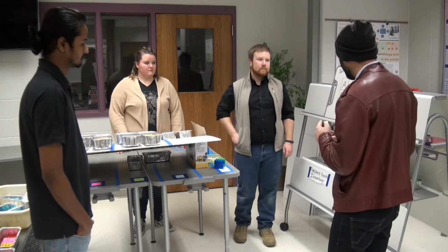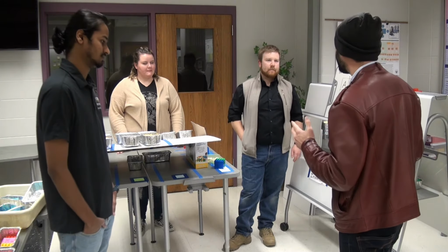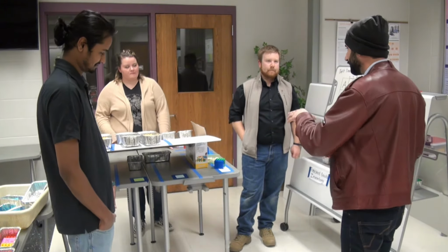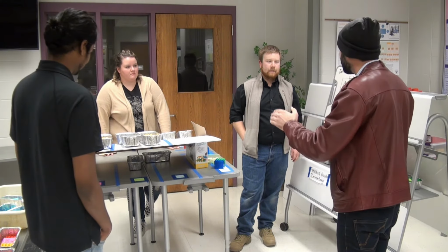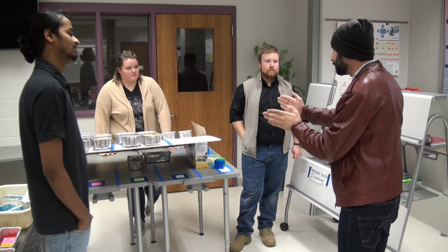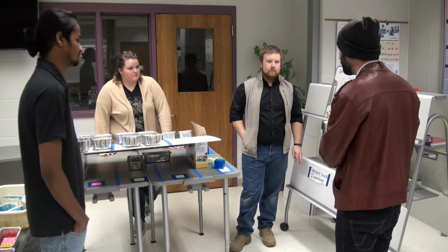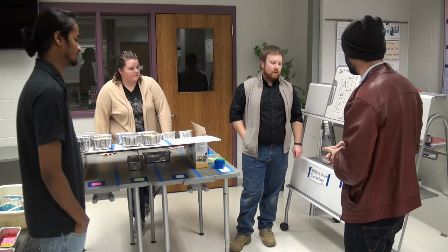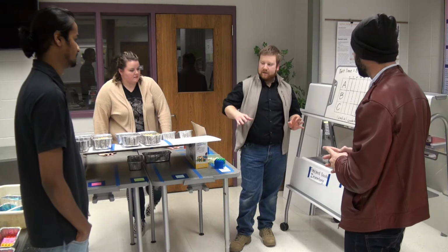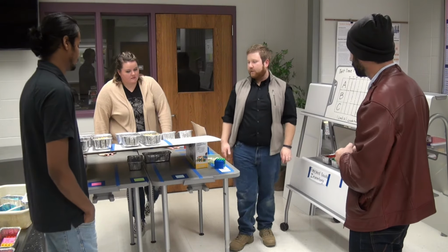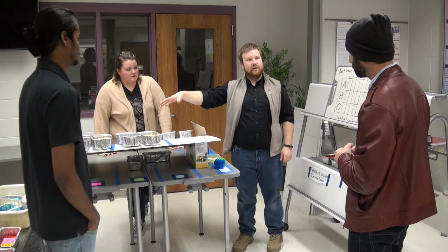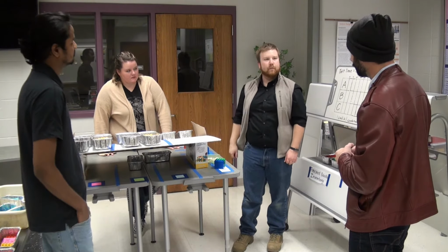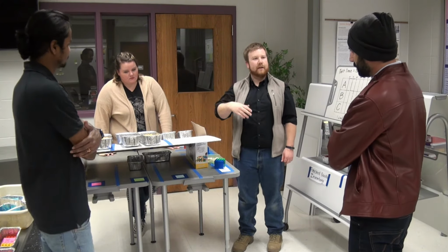Awesome. But I do have a question. If you notice lean, most people would say lean means 0 or no inventory or reduced inventory. So I see that one of the changes we made is we kept a little bit more inventory than we had in round 3. So does that mean we need to have more inventory in order to keep customer demand, or is there any other way to mitigate that? Correct. The major change between this round and the previous round, round 3, was that we did a calculation to understand the necessary material to have here on the flow rack so that Sarah would never be starved of parts. Right. And we figured out that that was 4 containers of each.